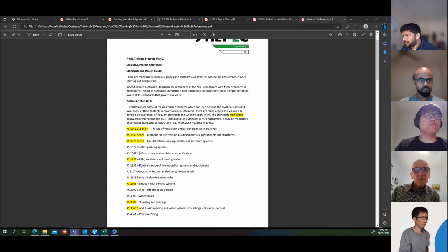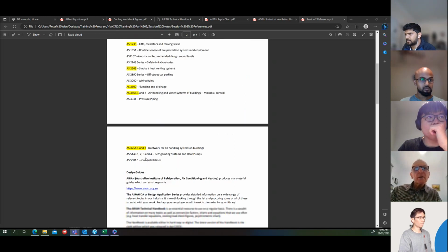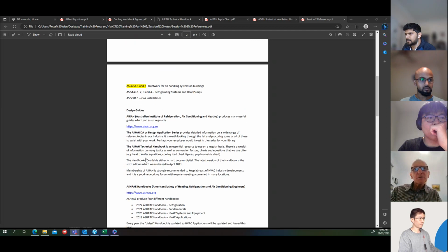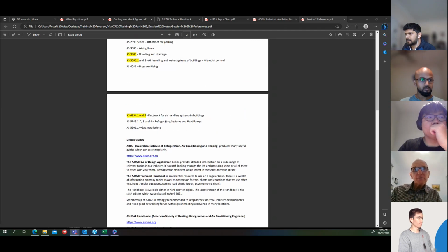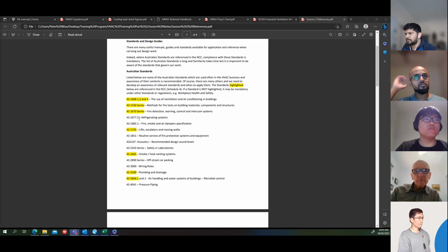AS 1677 Part 2, refrigerating systems. This also applies to obviously refrigeration systems for HVAC. And it's almost superseded. It's not gone yet, but there's a part of it that's still relevant, which is Part 2. I'll just skim down quickly. AS 5149, Part 1, 2 and 3 and 4, refrigerating systems and heat pumps. That's now the standard that's taking over from 1677.